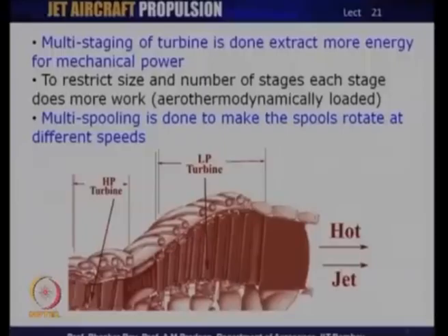So, the turbines which drive the compressors directly through a concentric shaft also need to conform to this restriction of rotating speeds, and as a result the LP turbines need to be rotated at a somewhat lower speed than typical HP turbines. So, these are some of the fundamental reasons for multi-staging, and these reasons allow the aircraft designer a lot of flexibility in design and in the operation of the typical aircraft engine, and these operational flexibilities are what need to be designed into the aircraft engine gas turbine.